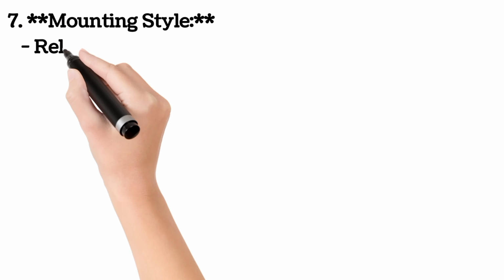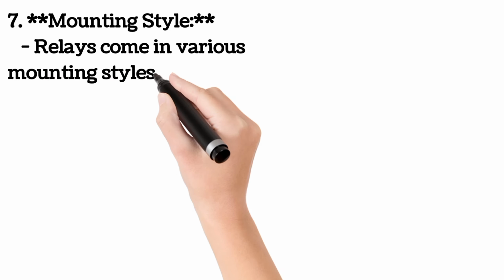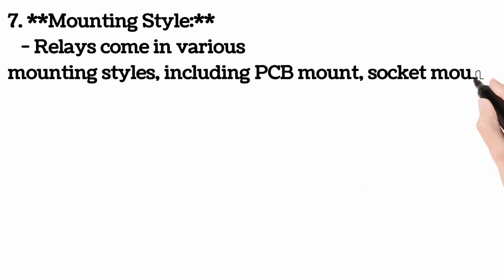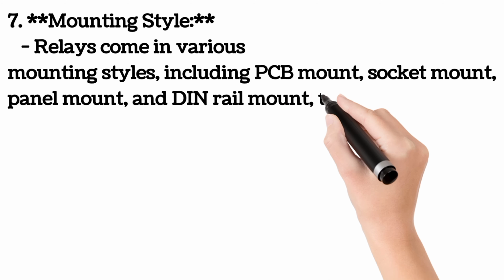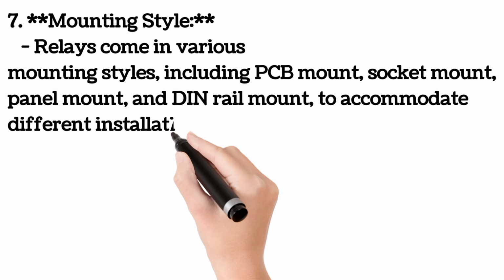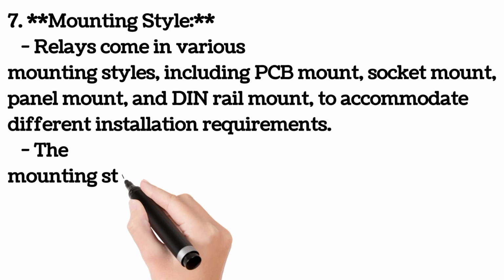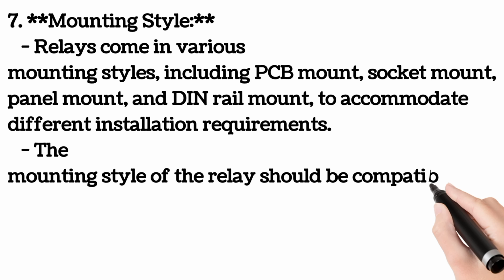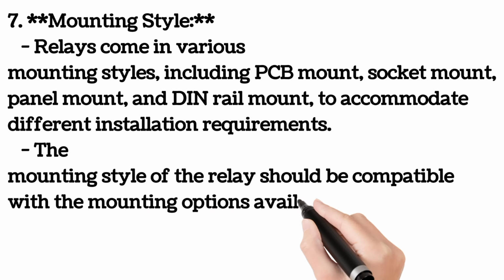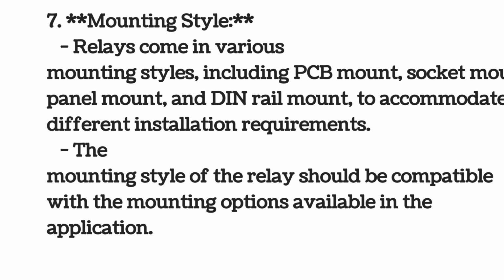7. Mounting style. Relays come in various mounting styles, including PCB mount, socket mount, panel mount, and DIN rail mount, to accommodate different installation requirements. The mounting style of the relay should be compatible with the mounting options available in the application.